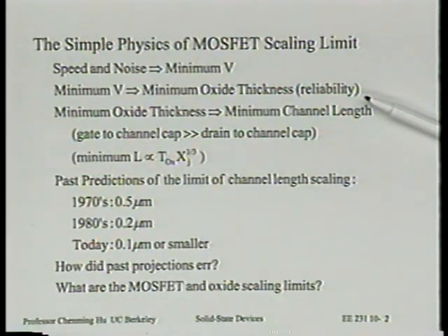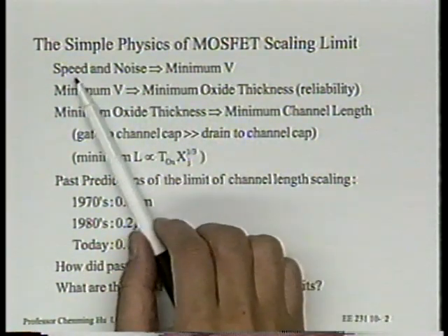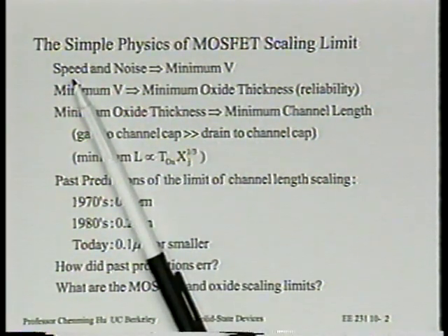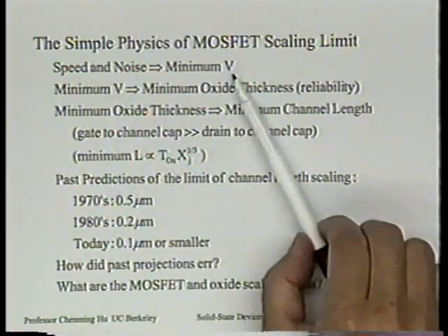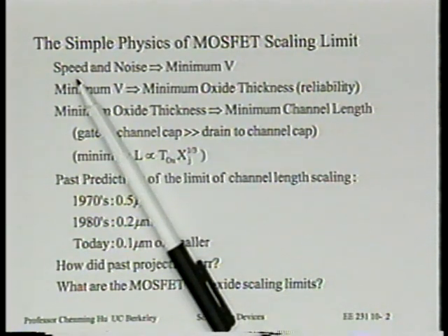It seems like the selection of 1 volt is very much a function of VT. So if you could have everything, let's say there was no leakage issue, and you had very reliable transistors with 0.1 volt VT, then you could actually operate circuits more easily at less than 1 volt. Correct. That statement is correct. One of the reasons we cannot use a lower power supply voltage is because of speed, as we said, right? And so the comment is totally correct. The reason we cannot accept arbitrarily small voltage and still maintain speed, one of the reasons at least, is that we cannot accept arbitrarily small VT.